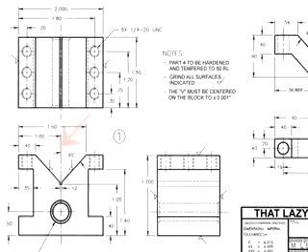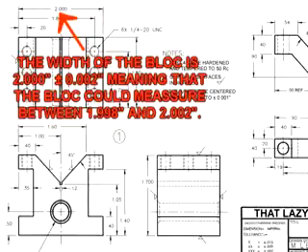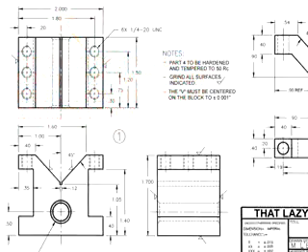Since symmetry is about the center line in this case, well, the block's width would have no effect on how to position the V on the block if geometric symmetry tolerancing was applied. And that is the beauty of geometric tolerancing.